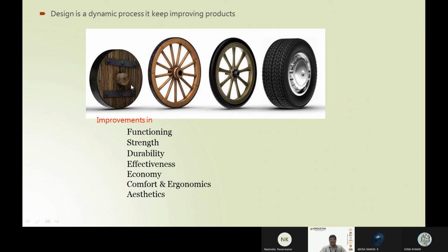Can you tell me what modification they made in the second wheel from the first? So the size and thickness. Okay, the size and thickness, they are going for a bigger circumference, it will be easy. The thickness, yes, that is a very important thing, right? You pointed out the first one was heavy. The second one is not so heavy. When compared to the first, the second one is very good in terms of weight, and you are having many slots, right? Instead of being fully covered, it has some slots and is connected properly, so that it will be good. So these are some advantages when compared to the previous one.